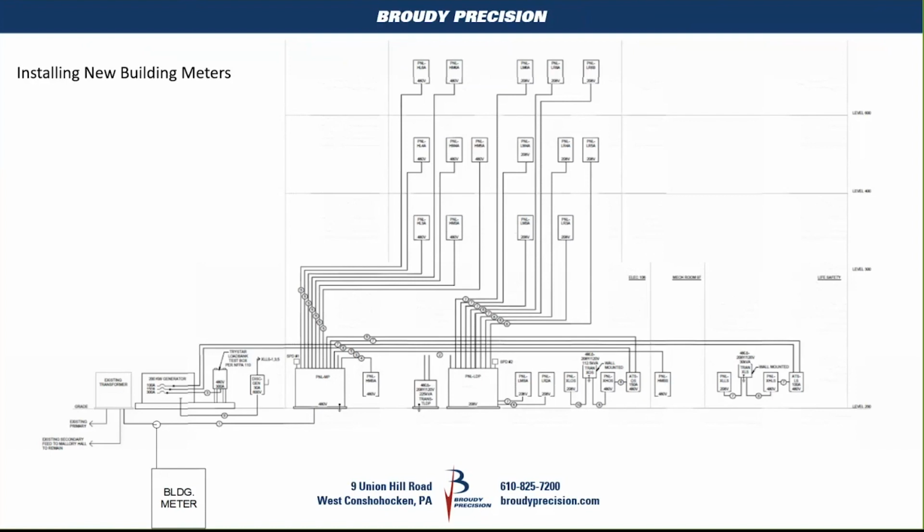You can see on the very left, the primary that's going into a transformer. So that's your high tension coming in. It's transformed down to 480 volts, and that's where we stick our meter. That is before anything is taken off of the transformer, we have our meter.